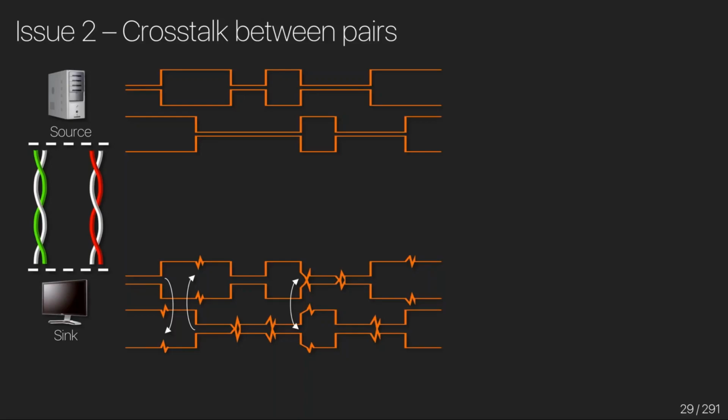So what can we do to avoid this? Ultimately, the solution is to use shielded cables. So you want the wire pairs to be shielded from each other. In a DVI and HDMI cable, that's how they're designed. They're standard for this. So once you wrap the cable in something like aluminum foil or a suitable shielding material, the noise won't get through to the cable inside.